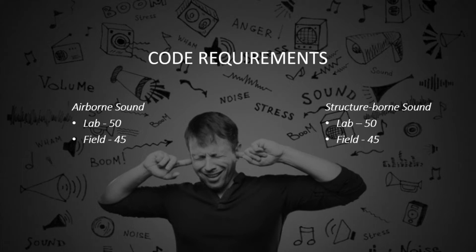So then the code requirements, right? Within the International Building Code, we have requirements for airborne sound, right? And for structure-borne sound. And the laboratory requirement is a 50. So if you're looking at a laboratory test report, it's got to be at least above a 50. And for field, it's a 45. And that's the same for both airborne and structure-borne sound.